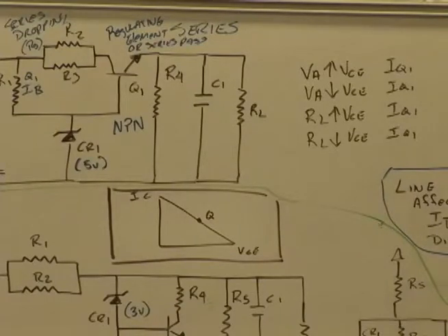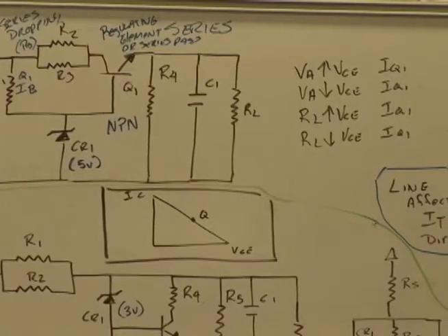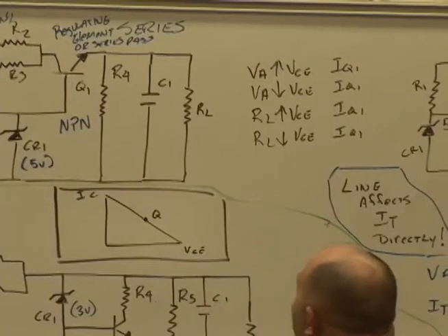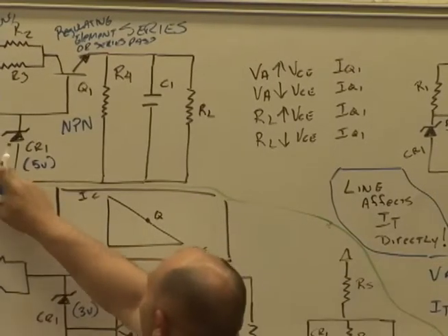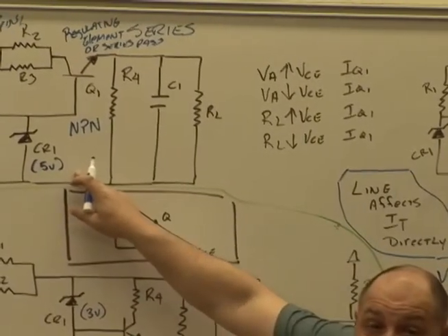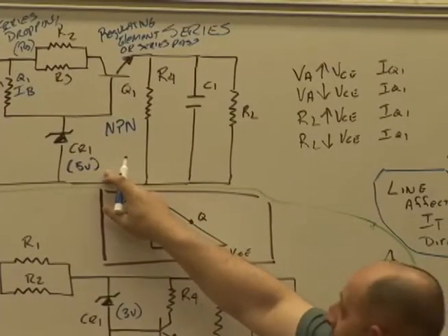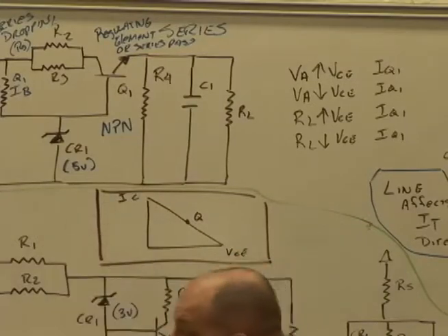And even in this circuit, VCR1, look at that. Doesn't this establish the base voltage for this one? Yeah. And guess what? The base voltage is not going to do much of, rhymes with change. Not a whole lot. CR1, that's our zener, isn't it? Yes, sir. And we know what it does by now, don't we? It helps set the output voltage, V out.